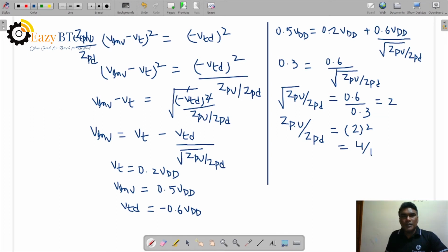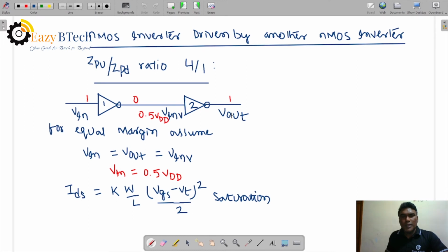You see this one, for example, it is in transistor representation, so that you can understand this. What is a pull up pull down ratio? This inverter, as we discussed yesterday, is designed by a depletion mode transistor and an enhancement mode transistor, both in series connection.